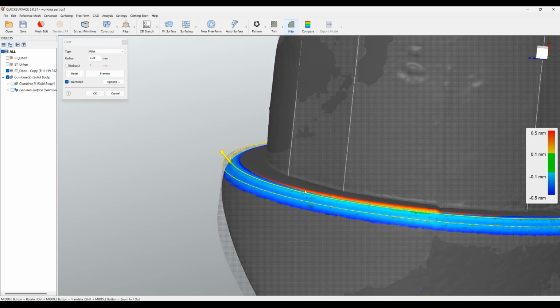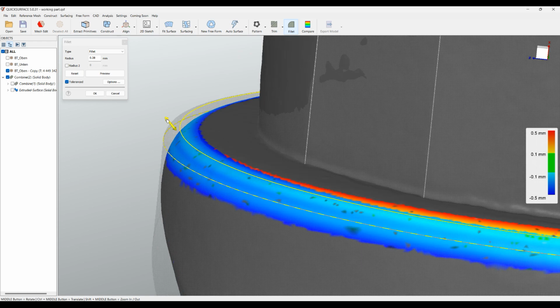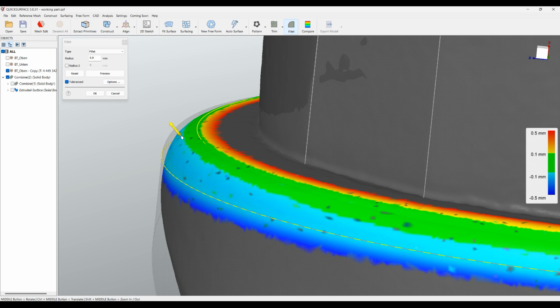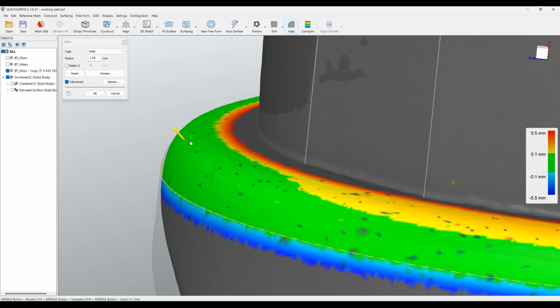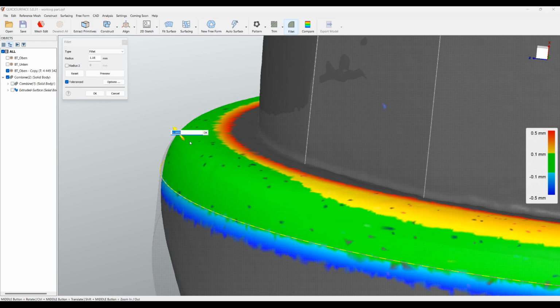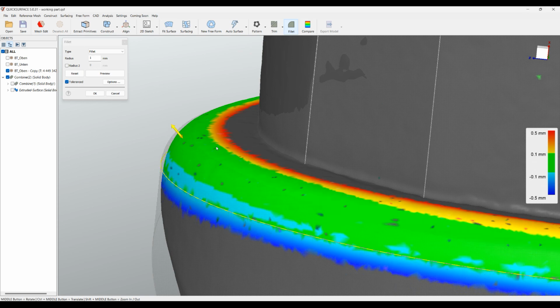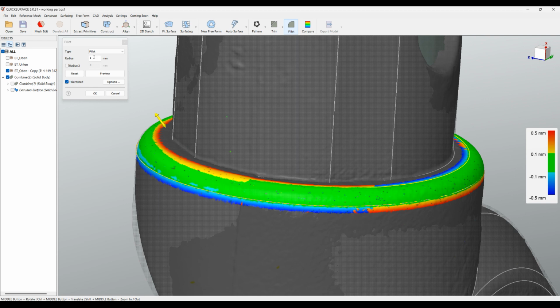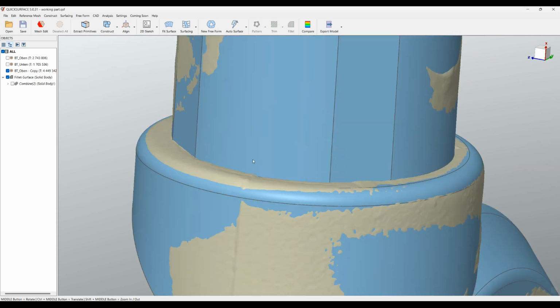This will give you a good indication how close you are. For example, in real time I can just move and figure out what actually the fillet should be. In this case it's 1.16. I can probably put it 1 millimeter. Maybe this is good enough. I can just press OK, and I'm still within a good tolerance, which means that I can just leave something which is logical for every manufacturer. When I'm happy with this, I can just press OK.